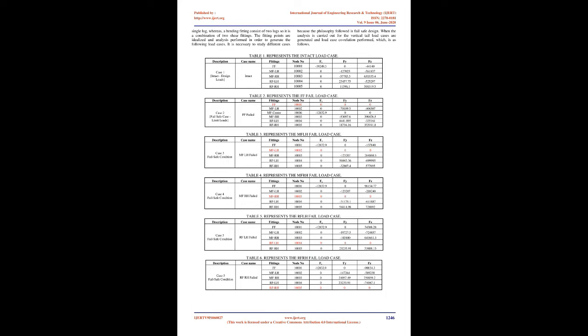3. Methodology. Designing and analysis of the shear fitting involves performing the classical calculations of failure of the lug under different loading conditions, creation of the CAD model, performing finite element analysis with the 2-dimensional and 3-dimensional idealizations of the elements, and finalizing the minimum necessary dimensions for the fitting.